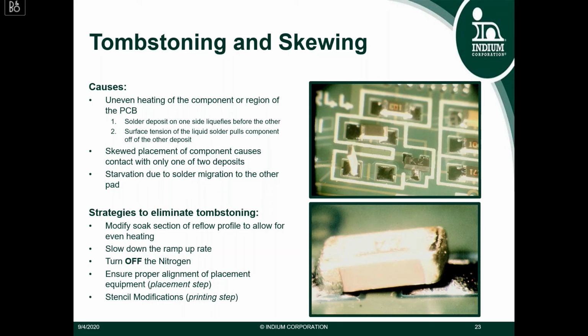And also, if there's too much paste printed on the two pads, as they are reflowed, the solder paste deposits connect together underneath the component. One of the solder paste pads could pull solder paste away from the other pad. When this happens, you have more solder on one pad versus the other pad. This will also create an imbalance of surface tension forces on the component, which can cause it to tombstone.